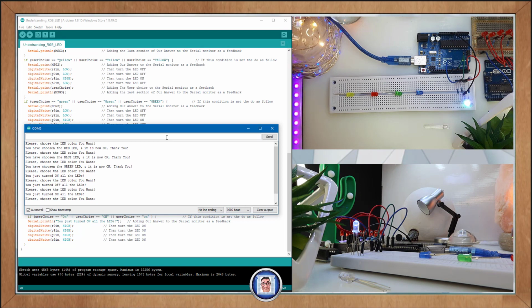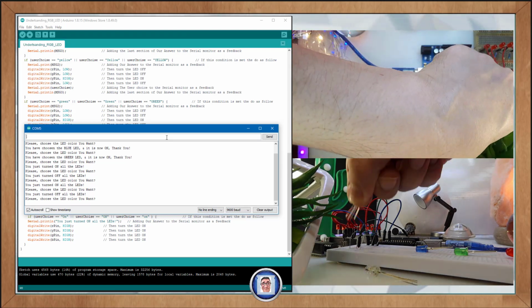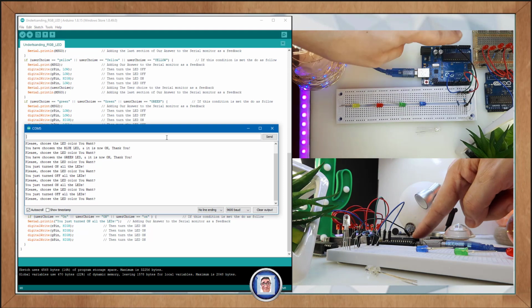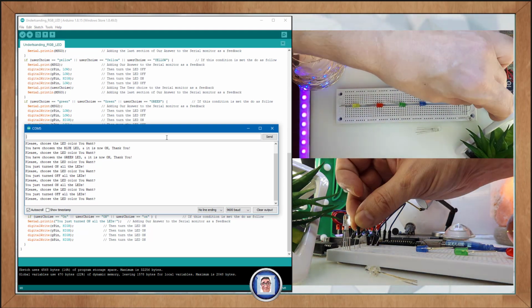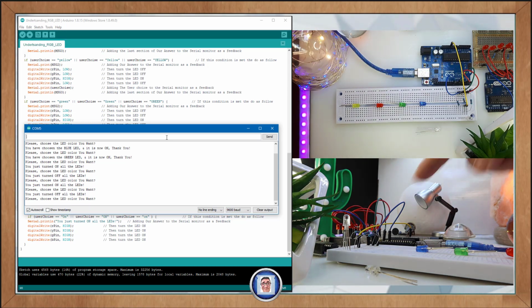Now it is time to try the common anode. We have to adjust the wire to the corresponding leads, of course. We will start by adjusting the leads in order to make them fit in the breadboard, and we will change the common black wire to a yellow one to make sure we understand that it has to go into the VCC or the 5 volt, like so.